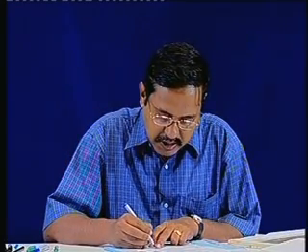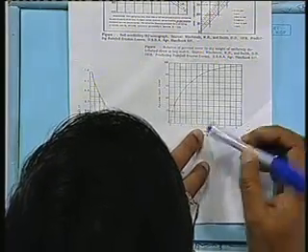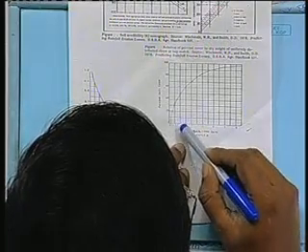This is just to reduce erosion. I have explained the importance of vegetative material in reducing erosion. So this mulch is generally put in terms of 1,000 pounds per acre. Suppose for a slope we have spread 3,000 pounds per acre of mulch on top of the soil slope. So it is 2, 3. You can see this, here 0, 1, 2, 3.